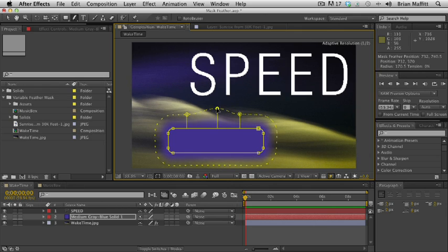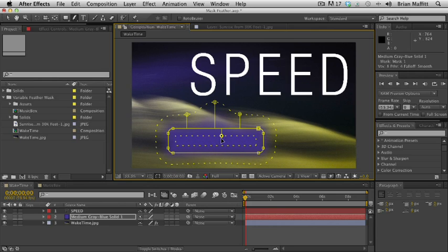Similarly, the up arrow increases the distance of an outer feather and decreases the distance of an inner feather. And once again, this can be surprising when your points are at the bottom of a shape. Takes a little getting used to, but you should pick it up fairly quickly. Shift Nudge moves more quickly. Select multiple points to move them all at once, by mouse, or by nudging.